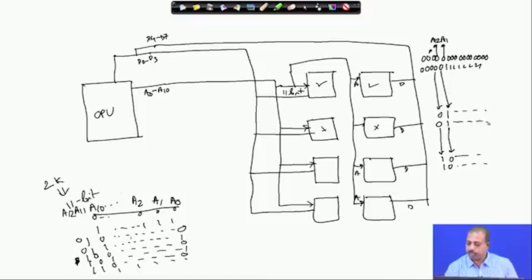These values can be anything. Similarly, for the fourth bank I want both these values to be 1. These are don't cares, whatever they are. So, this is the range of addresses that has to be selected for different values of A11 and A12, so that the module is selected.